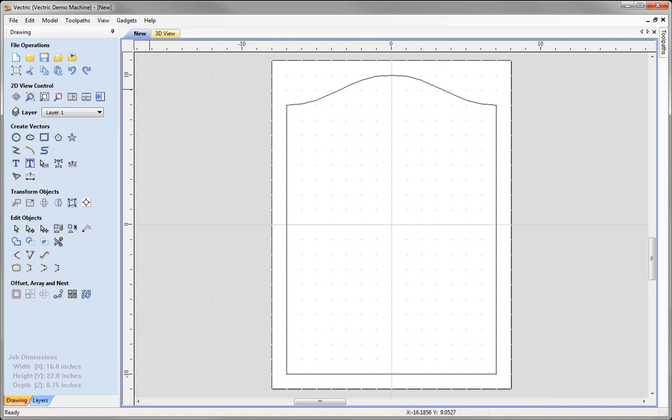So I know when I machine the outside shape of my raised panel that I'm going to use a specialist cutter, and that has a cutting width of 1 3/8 of an inch, and I have that information from the manufacturer of the cutter. So I'm going to take my outside vector and offset it inwards by that distance so I know where the edge of my OG shape is going to be around the panel. That'll also be a vector that I'll be able to use when I come to machine the part so I can profile around it.